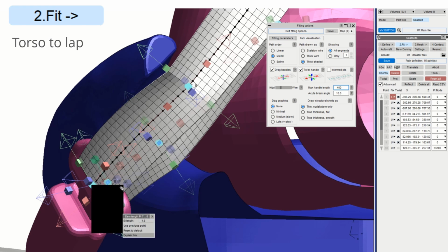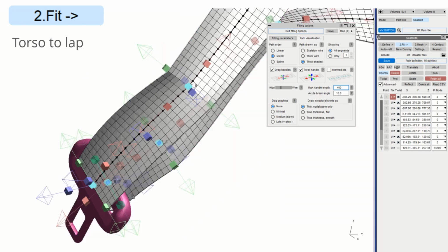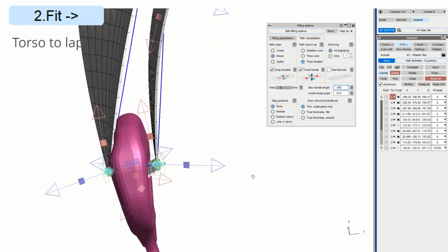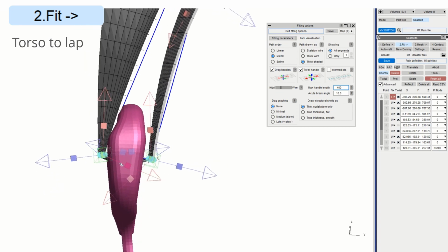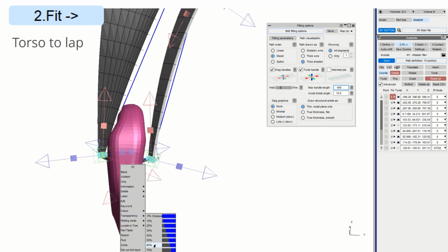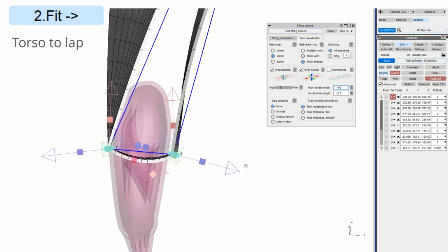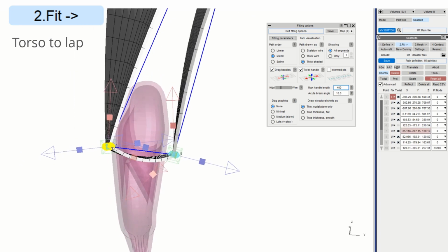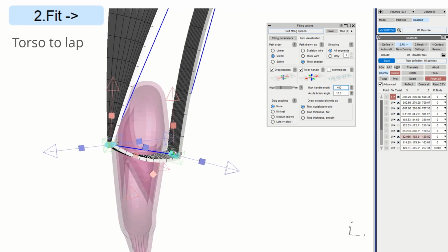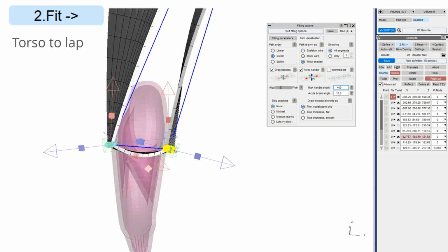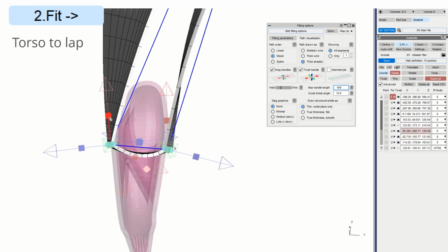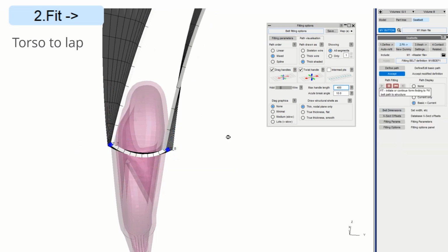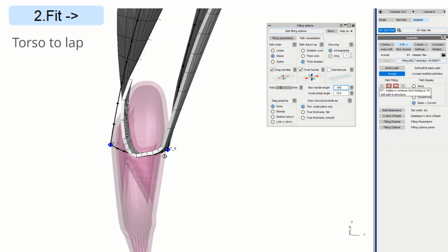We know we need a finer mesh through the slip ring. Just go and check that. Looks like we can move some points a little bit closer there. Again, setting transparency, looking down the axis of the slip ring. Let's just do a bit of fine tuning. No visual penetration, and a test fit.